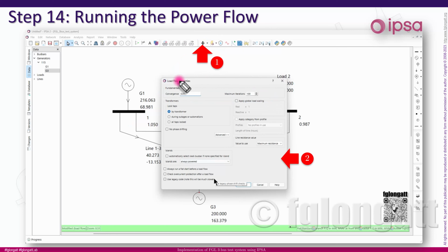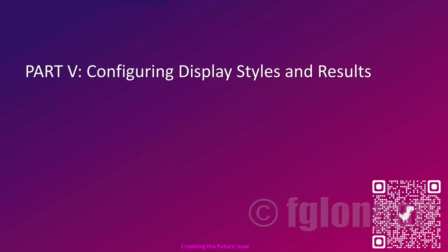For this video right now, I will not change any of these parameters. I will keep the configuration of the load flow properties as is, and I will just press the button over here. And when we do that, well, we are ready to get the results. And remember that IPSA has a very powerful graphic interface where you can retrieve the numerical results of your power flow by looking into the single line diagram.